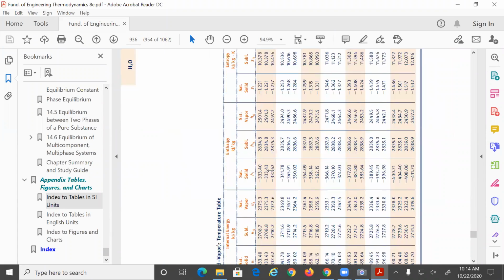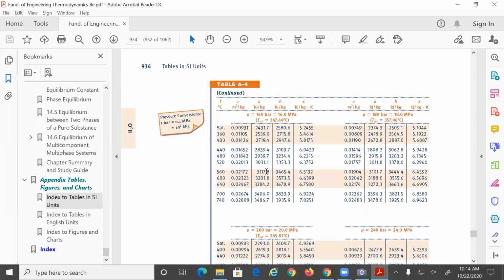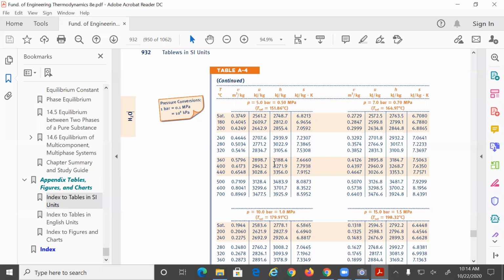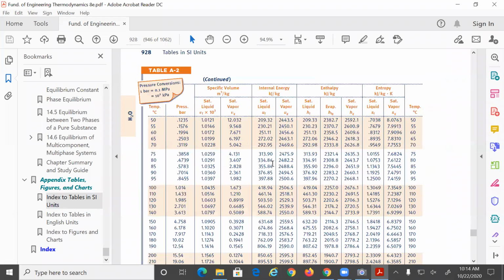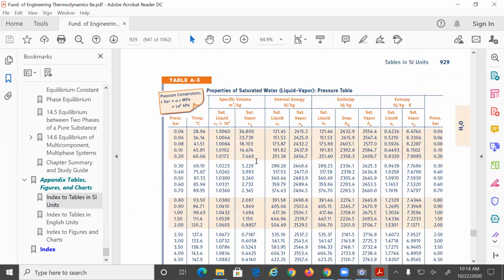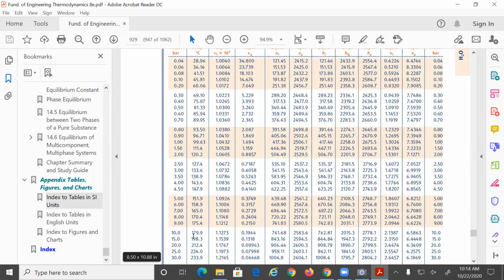Since we have this, I could just go and look at the values. Let's do maybe the first ones together. Let's look at the pressure 10, see if I have it in bars in A2 or A3. Is the temperature in bars here? Yeah, so for 10 bars, what is the minimum temperature? Saturation temperature is 179.9, no? So really, what is the state at point 2? It should be superheated, no?